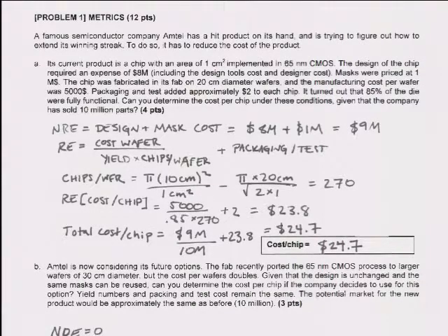So you divide 9 million by 10 million, you know that per chip, I'm going to pay 90 cents for NRE costs. Okay? Then the other part is how much do I pay per chip for the manufacturing? And there you have a number of components. The first one is the manufacturing itself, the silicon processing. The other one is packaging and test. Every time you have a package, that's a cost per die, and test is a cost per die.